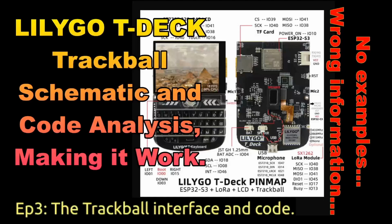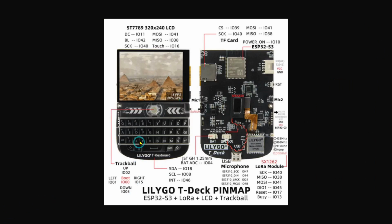In any case, when I started to look into that, as you can see, that little example in the background here, that graphic that I actually got from the LILYGO TDEC website, is actually wrong, which had me going in a loop for a while there. Yeah, so as you can see here, it's got the trackball, and it says up is GPIO 2, left is GPIO 1, right is GPIO 15, and down is GPIO 3. And of course, if you push the trackball down, it goes to GPIO 0.